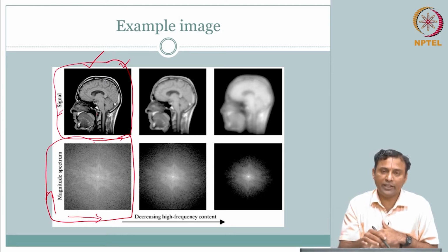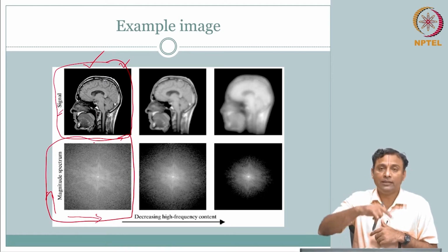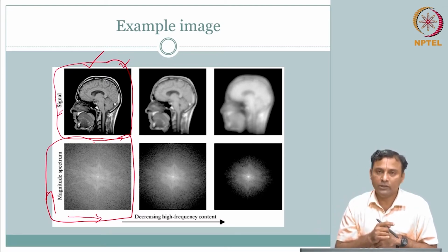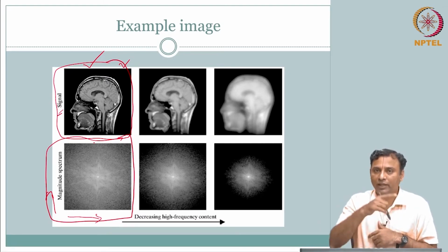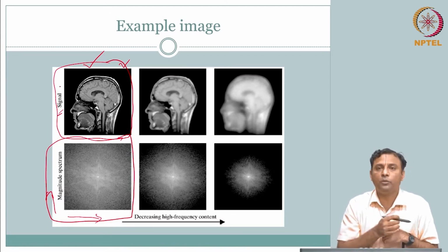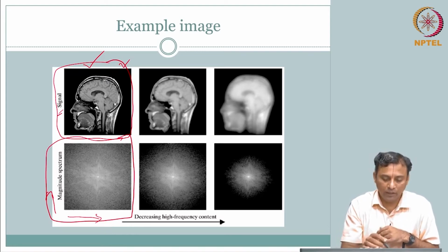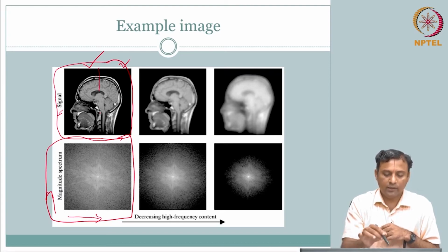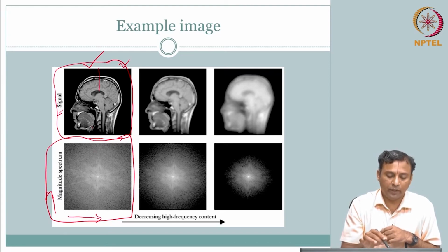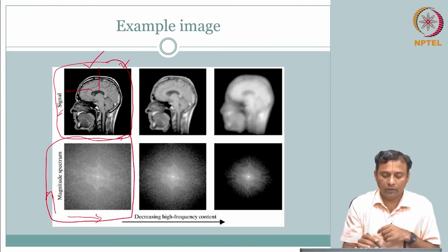Likewise, your intensity variation along the y axis, intensity as in the cyclic variation, black to white to black. Remember how we plotted that. The number of cycles going in the y direction is going to be your v frequency. If you look at it clearly, there is going to be white, black. So, there is a frequency in the y component, and a frequency in the x component, the u direction.